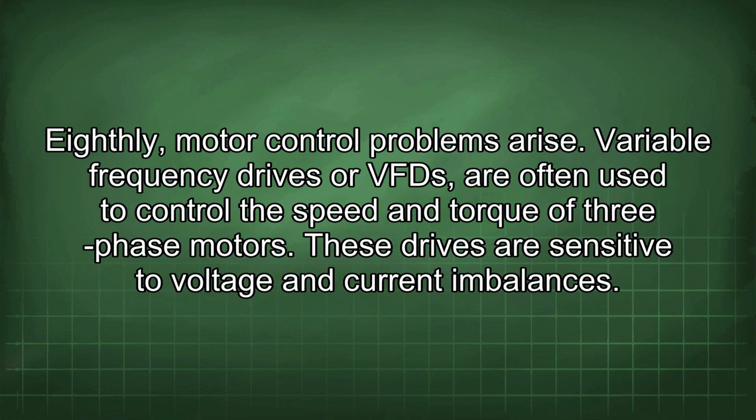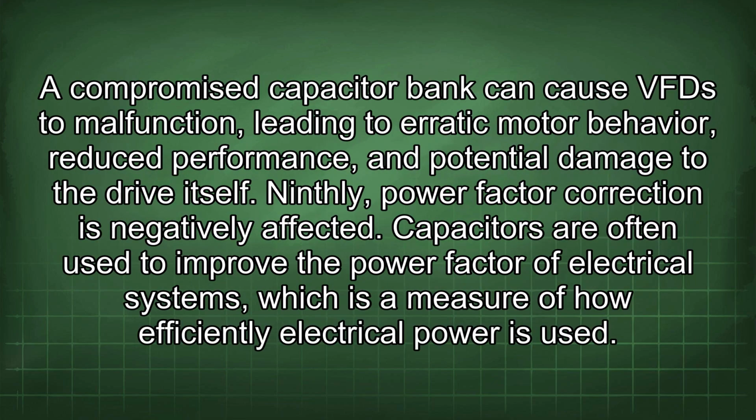Eighthly, motor control problems arise. Variable frequency drives, or VFDs, are often used to control the speed and torque of three-phase motors. These drives are sensitive to voltage and current imbalances. A compromised capacitor bank can cause a VFD to malfunction, leading to erratic motor behavior, reduced performance, and potential damage to the drive itself.